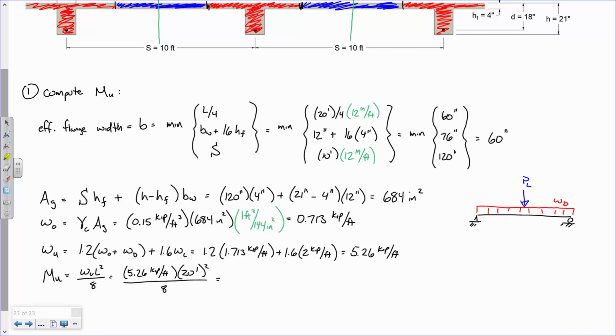you have to look at not only what's your difference in moment, but what's your difference in shear. Actually, the differences in shear can tend to be a little more, and it's actually more conservative to just use distributed load. But we haven't even gotten to shear yet.